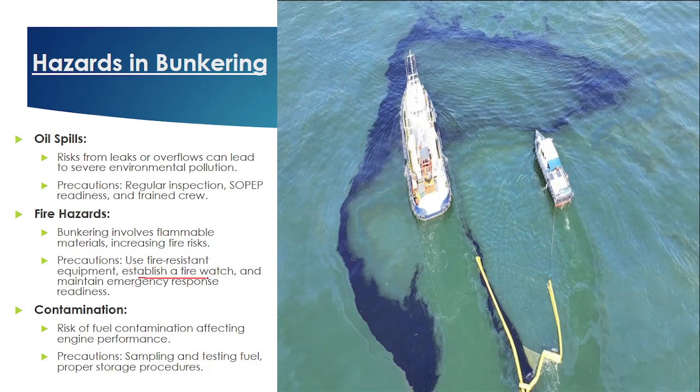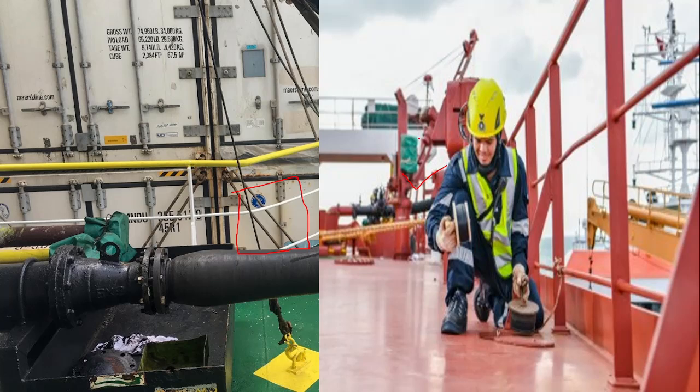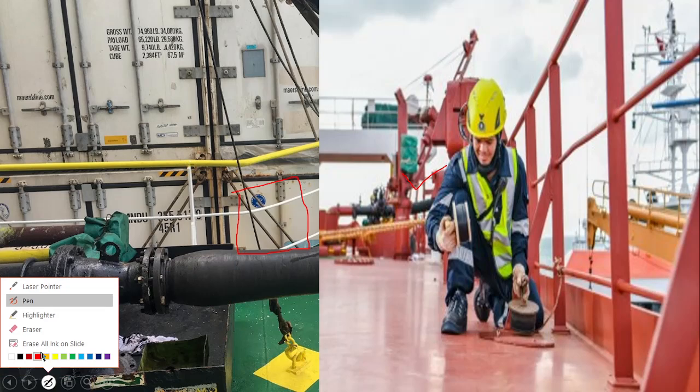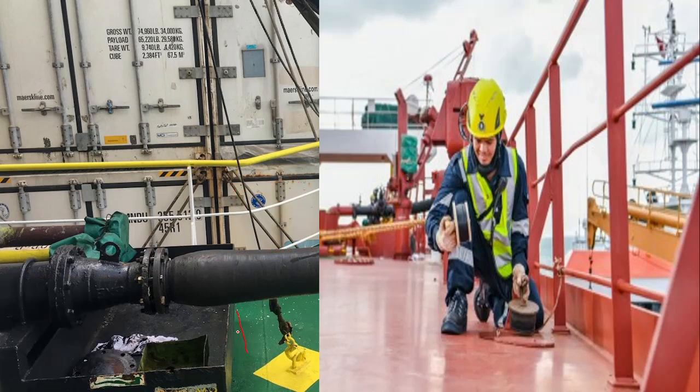Who will carry out the fire watch? The AB and the engine personnel who are not directly involved in the bunker operation should carry out a fire round in the engine room and on the deck in order to ensure that proper operation is being carried out. The second thing, as I have told you before, is that you should also keep one portable fire extinguisher nearby.